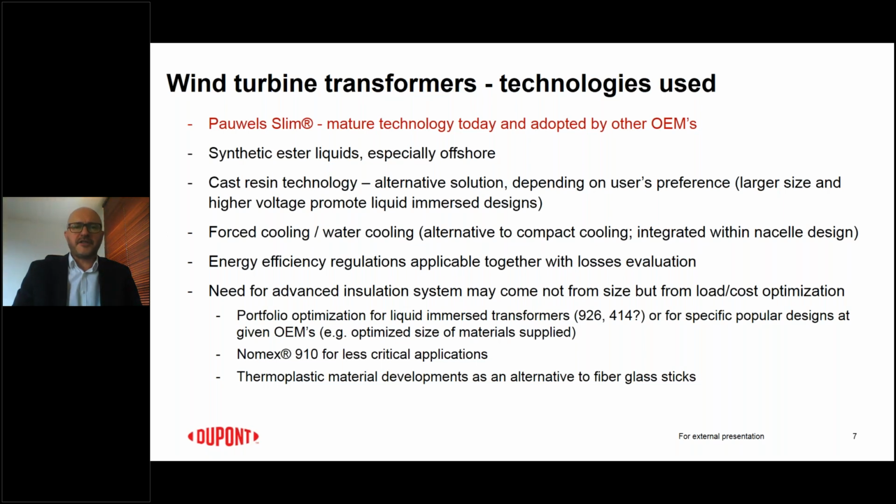But the experience shows that the users of the transformers, they still apply their capitalization of losses, and often the losses in the transformers are even lower compared to the official European regulations for the losses. So the cost of energy may justify going lower with the losses, meaning higher efficiency than prescribed in the regulations.